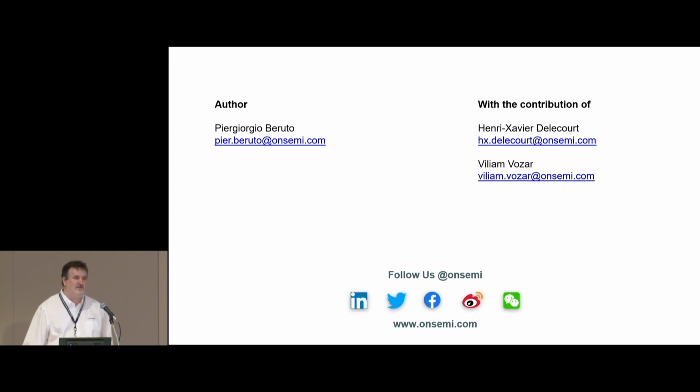That's a good question. Thank you. I didn't put the number here. Currently, the level of accuracy that you see here is obtained by integrating over a time window of roughly 1.2 milliseconds per node. This number is configurable. You can increase it to increase the precision, or you can decrease it if you want to speed up, and you get some less precision or some less immunity to noise.